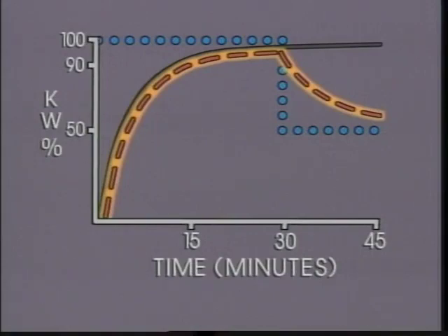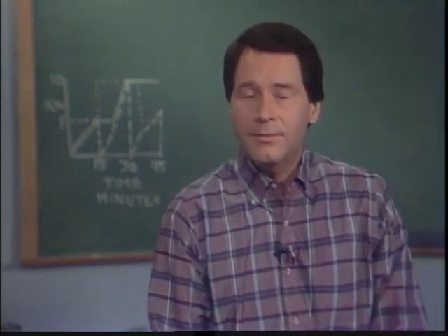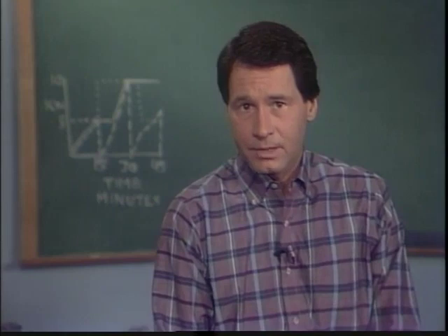Instead, it moves up or down scale in response to temperature changes resulting from load changes. For example, here the load decreased and the pusher arm moved down scale. Notice also, as indicated by the solid line, that the pointer remained at the maximum demand indicated before the load dropped. As with the mechanical demand register, the pointer will only be moved upscale if the demand increases beyond its previous maximum demand. So, with the block interval method, demand is registered in specific blocks of time, while with the lagged method, demand is registered continuously.